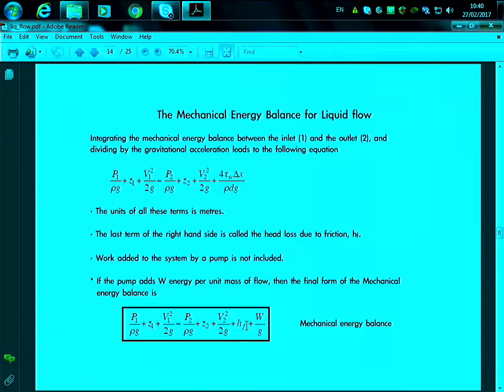Okay, so work in meters, which is very funny, but it's very easy to work like that in terms of the mechanical energy balance. So here we have the energy in equals the energy out plus the friction losses plus the work that is given. And this will be the general mechanical energy balance that we'll use for a liquid. This is how we're going to solve all the problems where we have a liquid going through a pipeline. Do you understand what all these variables mean?